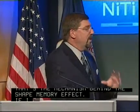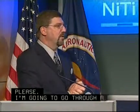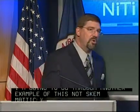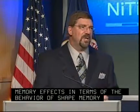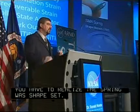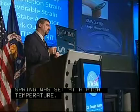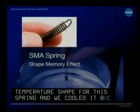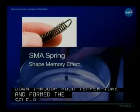I'm going to go through another example of this, not schematically now, but talk through the shape memory effect in terms of the behavior of a shape memory alloy spring. So first of all, you have to realize that this spring was shape set. That means the shape for the spring was set at a high temperature. So the spring shape is the high temperature shape for the spring, and then we've cooled it back down through room temperature and formed the self-accommodating martensite. So if we could go ahead and start the movie then.